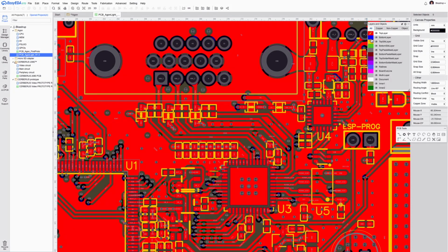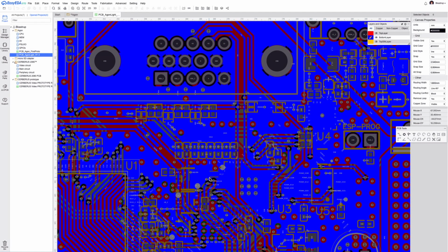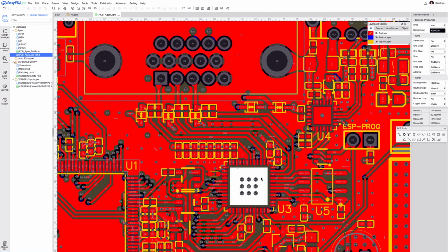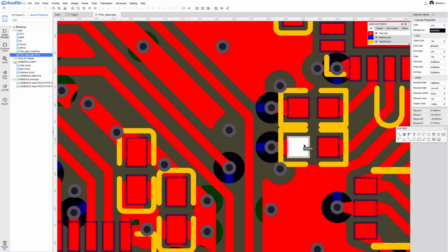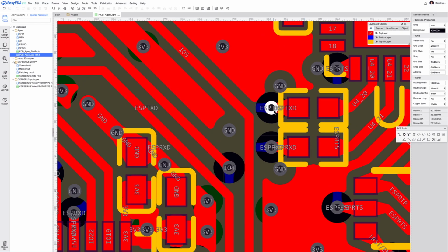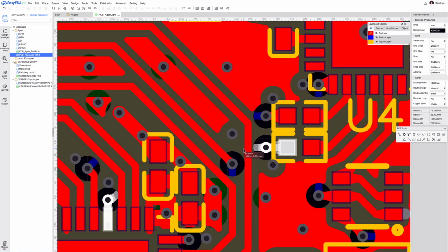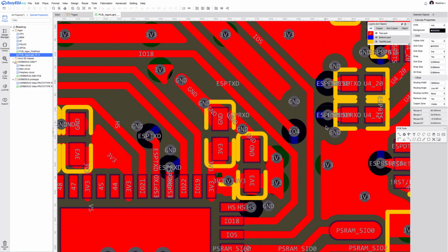Now, from the USB bridge to the ESP32, which is here, you can't see from the bottom layer, but the signals go this way, and then they pass through these resistors here, and then they go down to the bottom layer across the two inner planes, and from there they will get, let me see if I can show you just by highlighting. From there, see that you will get here to the input of the ESP32, and this one here to here, the input of the ESP32.